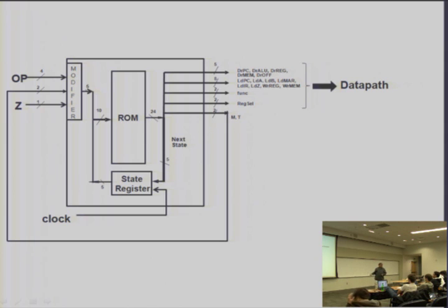And one thing that you can do is actually build what is called a micro sequencer that reduces that space complexity. And so in the project, there are 2 versions of it. The base version that I expect you to implement is, don't worry about wasting space, right? So first we want to get it right, okay? And so in order to get it right, just do it the vanilla way, which is using a simple circuitry for modifying the top 5 address bits when you need it, and not worry about the fact that you're using space in the ROM when you don't need it.